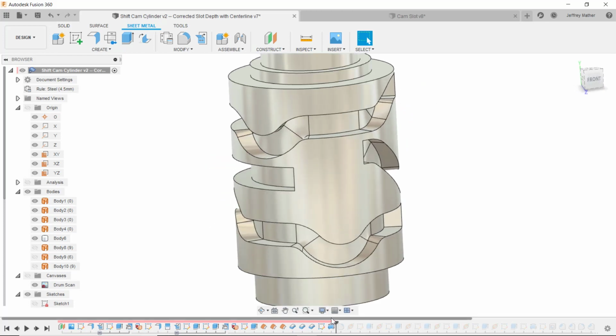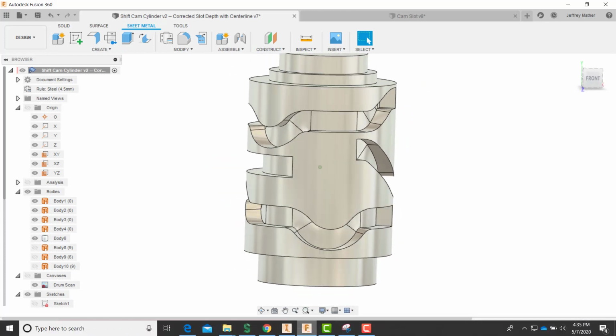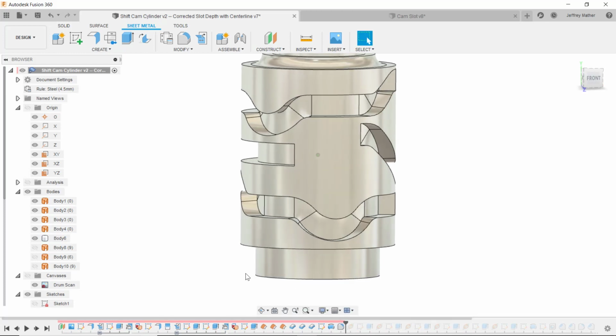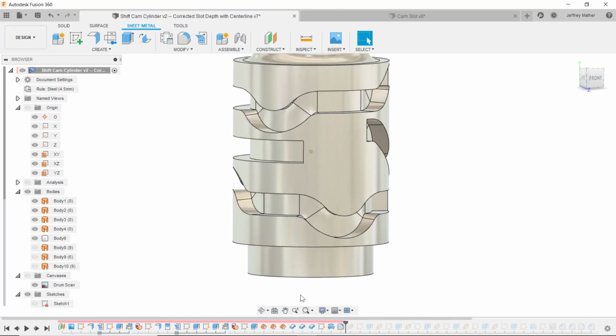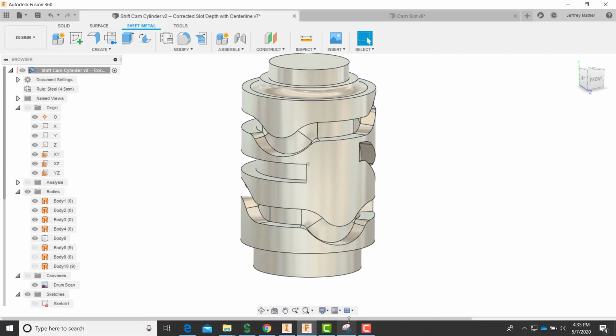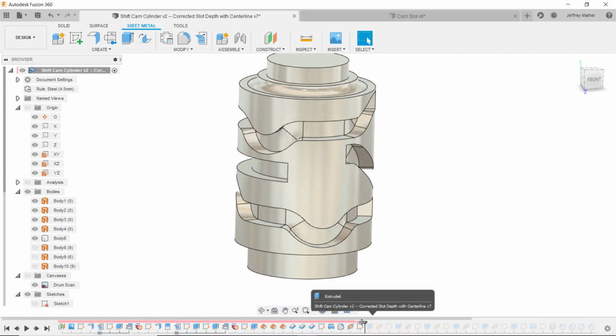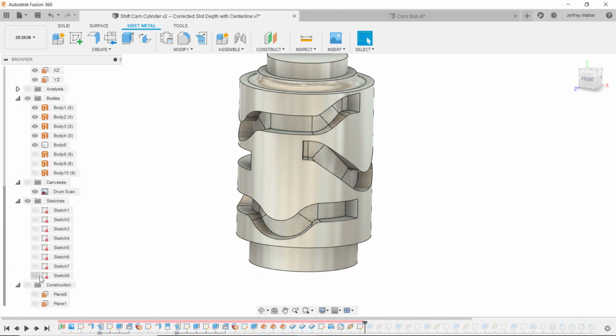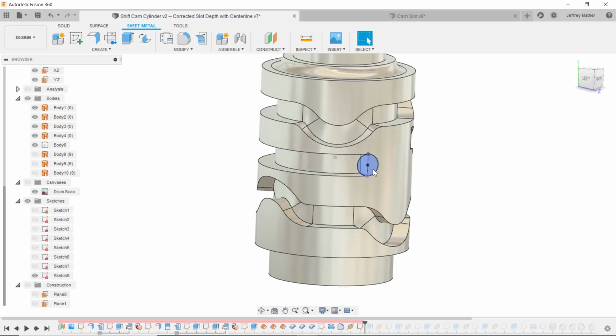Then in the next step, I put the top and bottom of the hub, and I could have put those in originally as part of that original extrusion here, and then put a fillet in here. I did a work plane here someplace, and we'll look at that work plane. Notice all of my sketches are fully defined. So I created a circle.